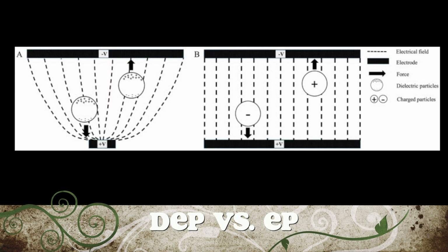So when protein particles are exposed to this non-uniform electric field, two different forces occur between the proteins and the surrounding medium, leading to a resultant force. So the motion of the protein particles can be in response to positive dielectrophoresis or negative dielectrophoresis effects, depending on the relative polarizability between the protein and the surrounding medium.